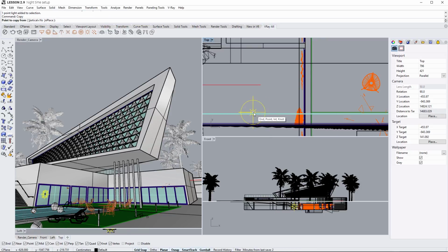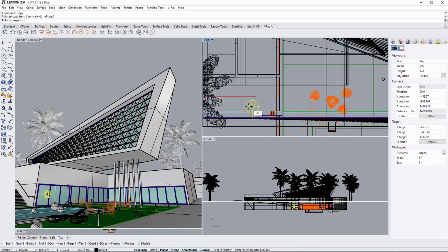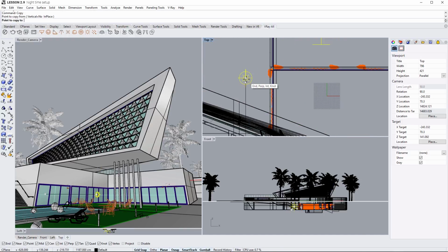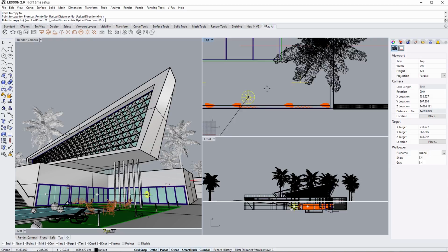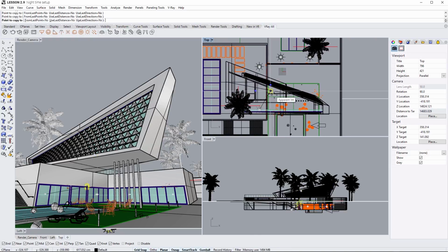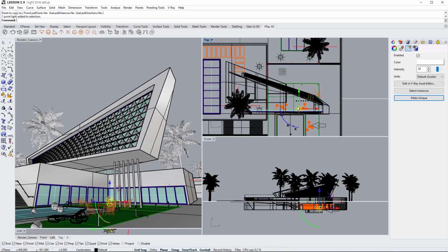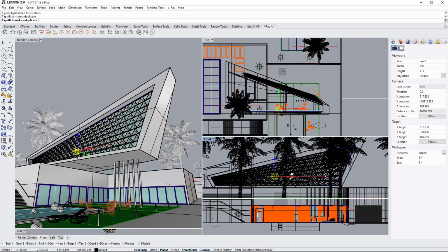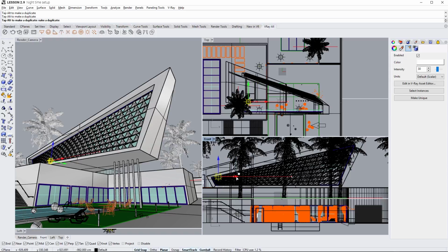Select the point light and use the copy command to create a few other instances of the light. In my case, I'll position them on the yellow guideline markers. Once you're ready with the lights on the lower floor, create one more copy to use for the upper floor. Then click the Make Unique button. This will enable us to have separate control over that light, to use different colors from the lights on the lower floor. Go ahead and move it up to the upper floor in the front view, and then make a few more evenly spaced copies to cover the entire upper floor.